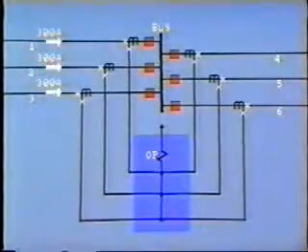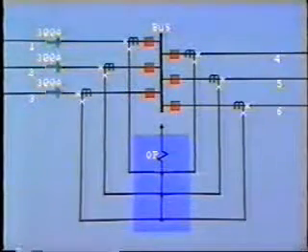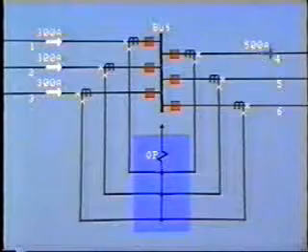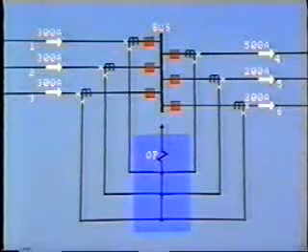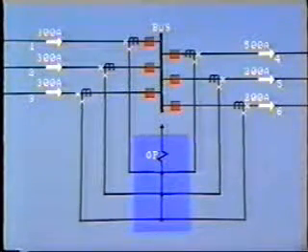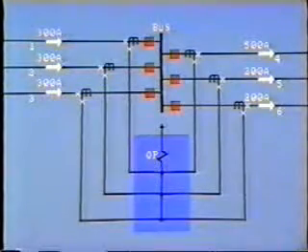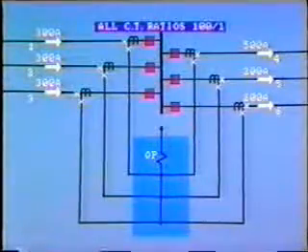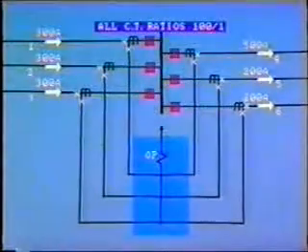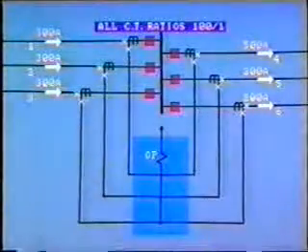There are 6 circuits connected to this bus with 300 amps entering on each of lines 1, 2 and 3. 500 amps flows out on line 4 and 200 amps out on line 5 and line 6. There will normally be a set of CTs and a differential relay for each individual phase. For good performance, all of the CTs must be of identical manufacture and the same ratio. For simplicity, we'll look at just one phase on each line. Let's assume this to be 100 to 1 for a rating of 500 amps primary.